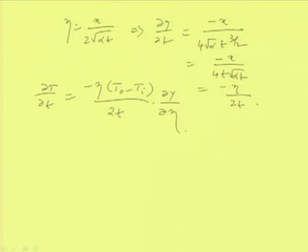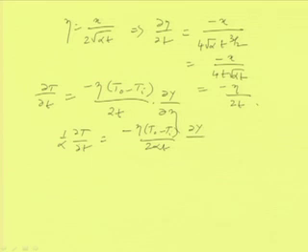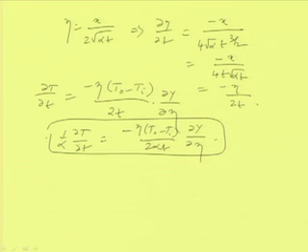Now, if we replace all these in the basic reduced equation, we get 1/α ∂T/∂t = −η(To − Ti)/(2αt) × ∂y/∂η. If we replace these values in the original equation, we get ∂²y/∂η² + 2η ∂y/∂η = 0, and as we know, y is now a function of η only.